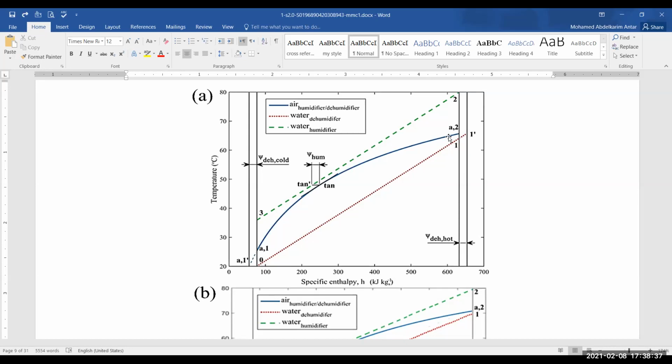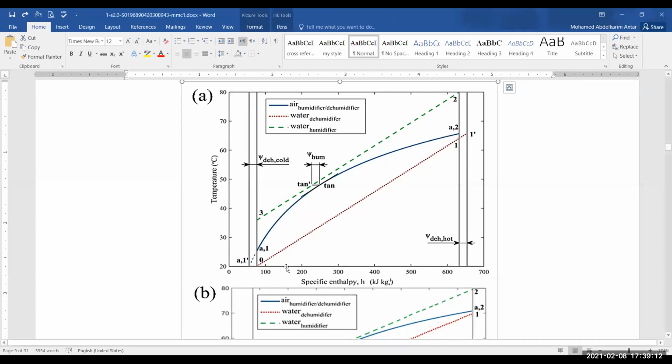And then we extended that work and we kept the same idea that we should satisfy the first law of thermodynamics and second law of thermodynamics and avoid the points of having negative entropy generation, which doesn't make sense physically, and so on, until we came up with this kind of expression. It's not straightforward when you are doing it in the analysis, because when you are solving or analyzing for the humidifier, you don't know exactly at which point this kind of local minimum is going to be achieved.